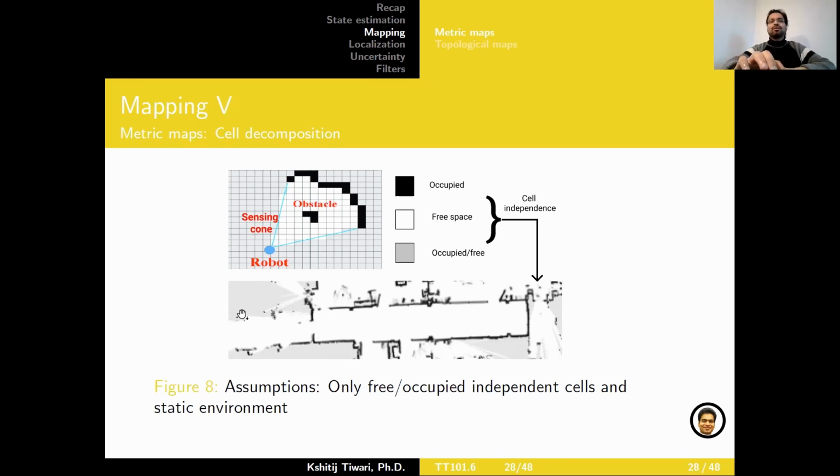And then depending on the quality of the sensor and the grid resolution, etc., you start to have a few different issues to deal with, such as this boundary might be a bit grainy and coarse. Maybe this is not going to be a continuous line if you have a very coarse sensor. If the grid resolution is too high, then you have too much computation to deal with. If it's too low, you're going to miss out on information, etc. So it's not really that straightforward, but as you can see, it starts to look quite a bit similar to a floor plan of an environment, and especially an indoor environment.